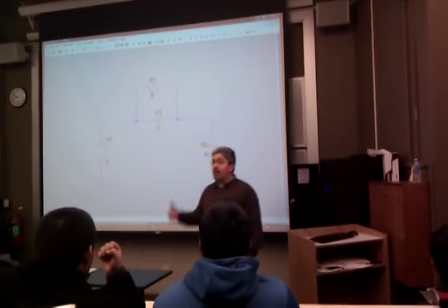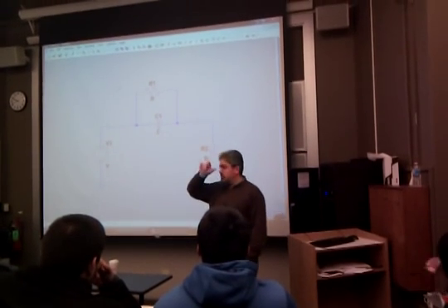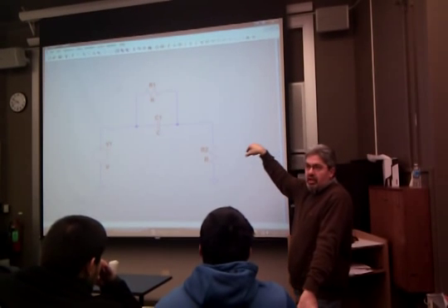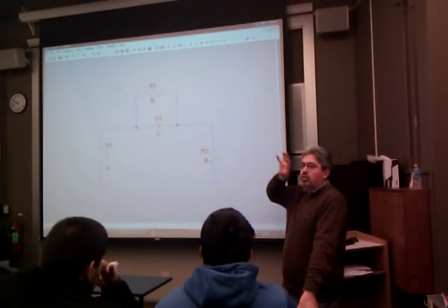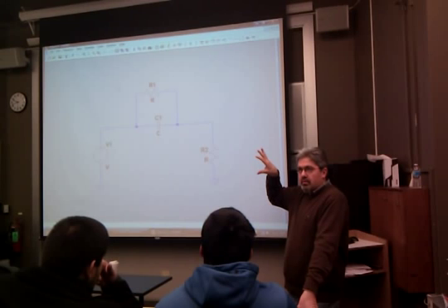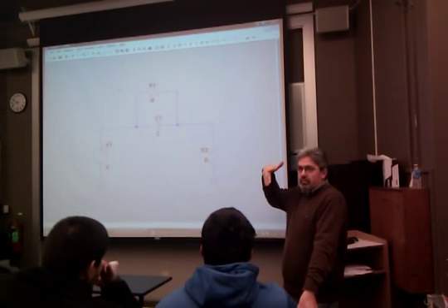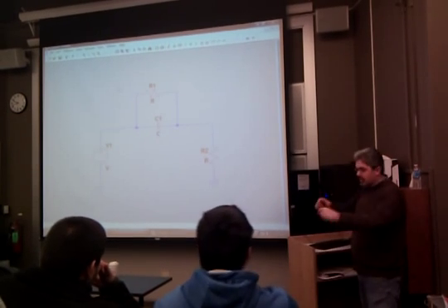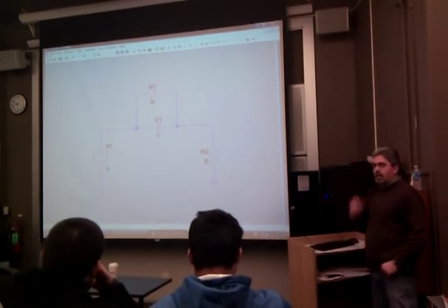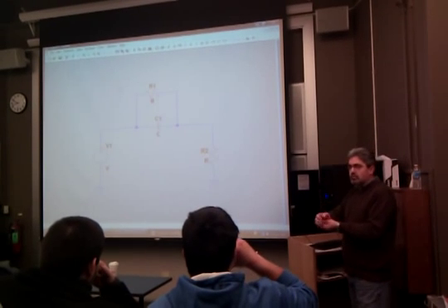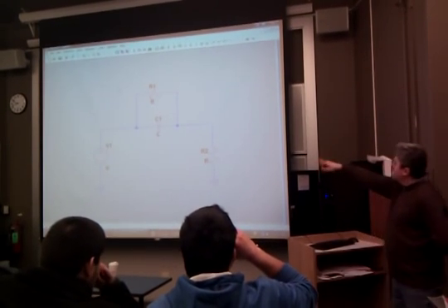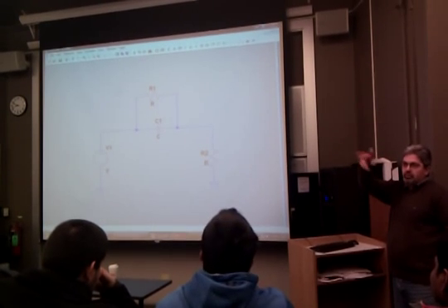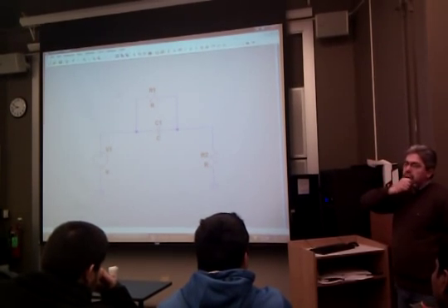There is no ideal op-amp in LTspice itself. However, if you go to the LTspice page, you can download an ideal op-amp. In fact, it's in the libraries, and I don't know if we'll have enough time to show it, but I can show that too. You go to the web page and download, and I'll show you that. Remember, I gave you those steps to go and install, and there's an ideal op-amp actually right there.